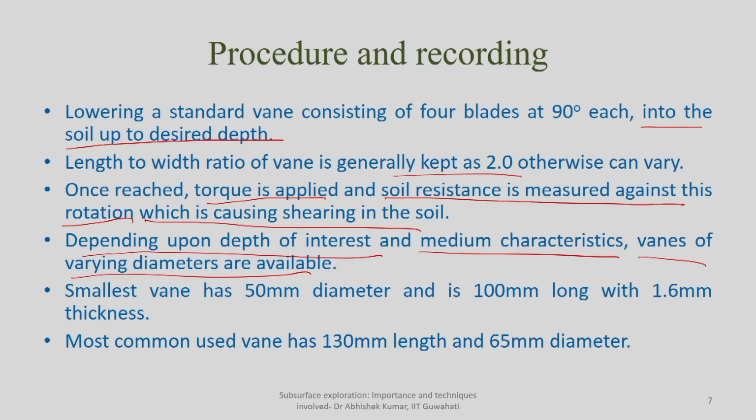The setup of the vanes is of uniform size, but as you go deeper and deeper, you keep on adding more drill rods. The smallest vane available is 50 mm diameter, 100 mm length and 1.6 mm thickness.